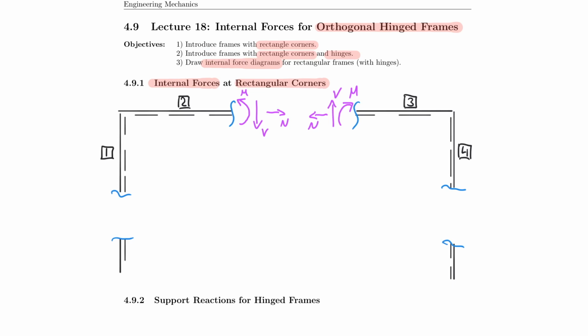So let us introduce our internal forces at that cut now. It's a left cut in this case, so my moment is clockwise. My shear force has to go up, which in this case is actually to the left, and my normal force has to go down.